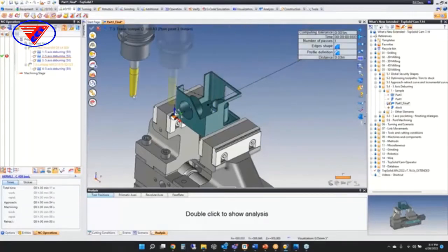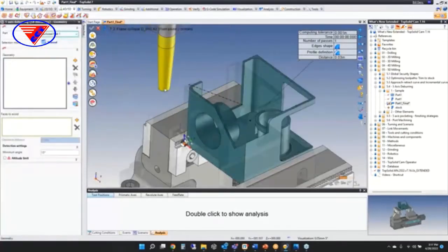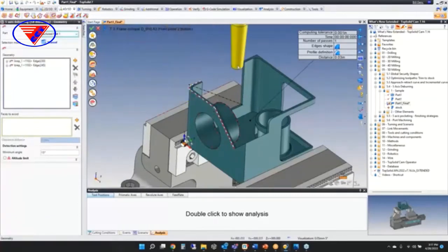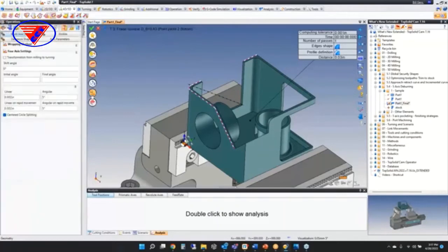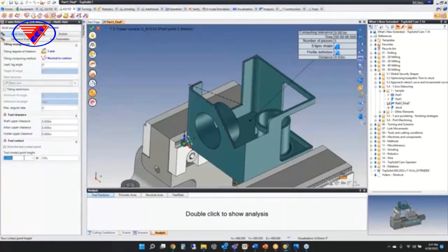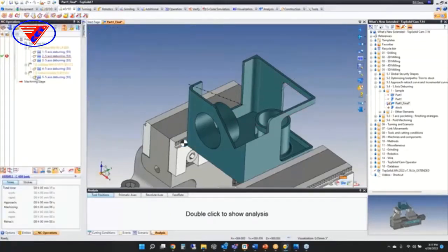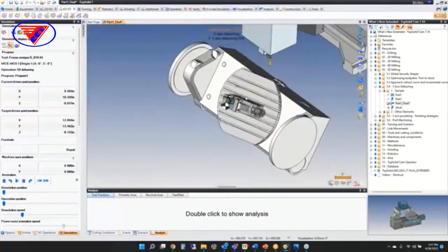And for my tapered end mill, really the only thing I'm going to do is set some geometries, right? So I'll select this one and maybe this one just for fun. And then under multi-axis, I'm going to set how far I want the tool to stick out past the bottom. That's it. And now when we watch that simulation,